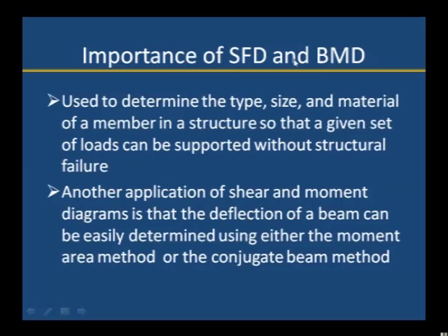Why do we need the shear force diagram and bending moment diagram? They are used to determine the size or type of the beam and which material we have to use for constructing the beam. Another application of shear force and bending moment is to know the deflection, that is, the extent to which the beam deflects under the load.